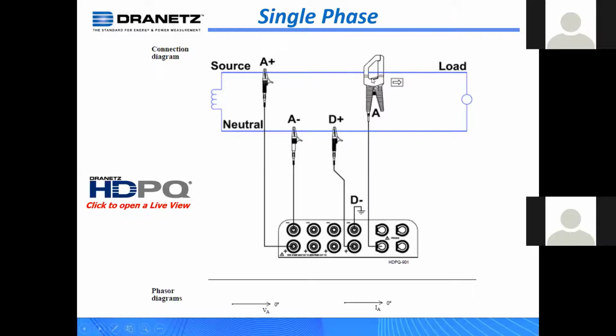So how do I get these things connected properly? You need your voltage and current to be connected properly. The one thing to note on a single phase circuit with a power factor of 1, so the voltage and current are in phase: if you look at the bottom, you'll see this. It's actually on screen on all of our HDPQ Plus and other family products. You can look at the difference between the angle of the voltage and the angle of the current. So with no power factor, they ride right on top of each other. They cross 0 at the same time. So if you see the phase relationship between voltage and current being 0, or something with a reasonable power factor, you know you're connected properly.